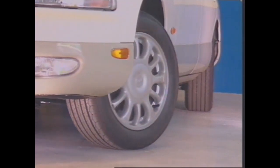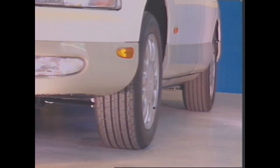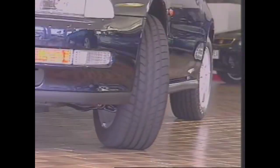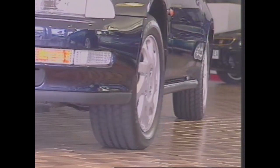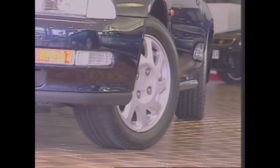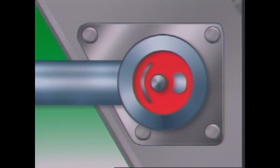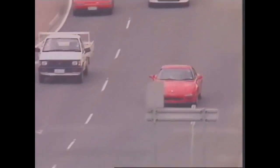Some cars have four-wheel steering. This can be computer-controlled, or it can be mechanical through a direct connection between the front and rear steering boxes. Or the rear wheels can be mounted on special compliant mounts. As cornering forces are applied to them, they alter the steering angles.